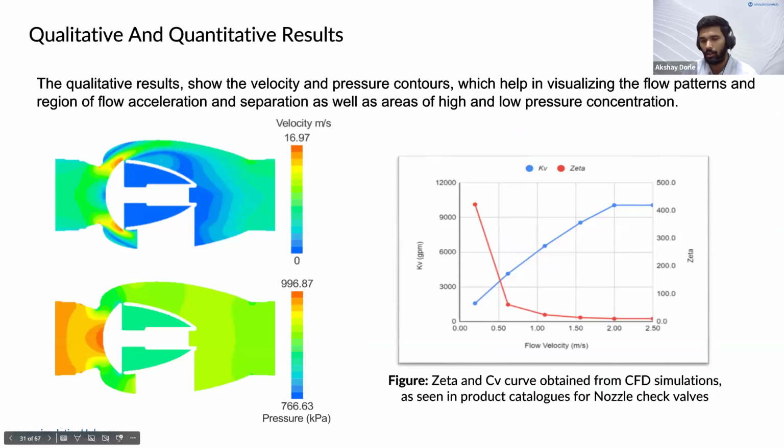So as we have seen earlier in the slides where we discussed the parameters, or what's printed by valve manufacturers in their catalogs, there was a zeta curve, there was a CV curve. Again, CV and zeta curves can be obtained for the valve using AVC. Not only for full opening, you can actually get it for all the intermediate openings as well. So again, this becomes very essential.